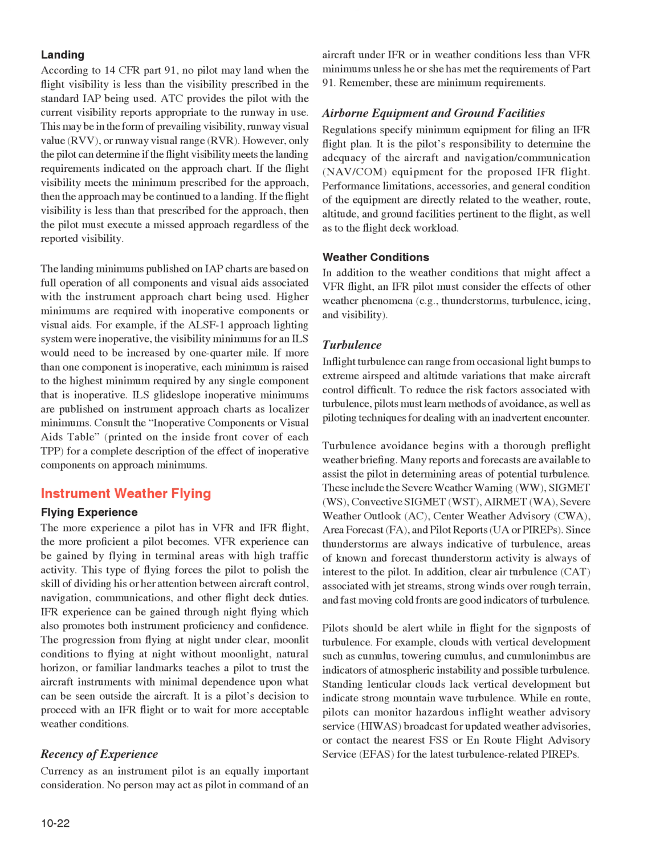If the flight visibility meets the minimum prescribed for the approach, then the approach may be continued to a landing. If the flight visibility is less than that prescribed for the approach, then the pilot must execute a missed approach regardless of the reported visibility.